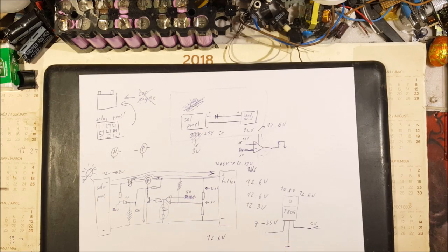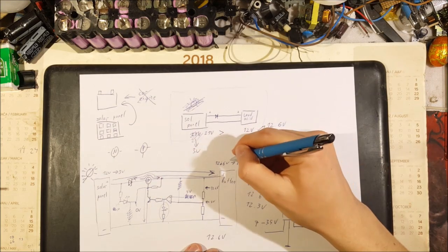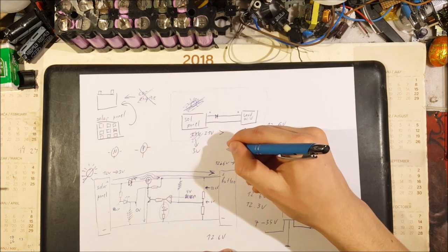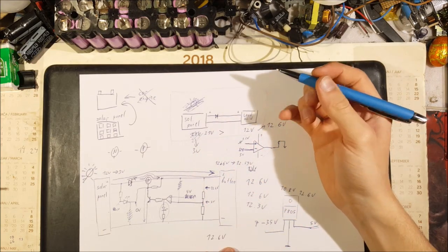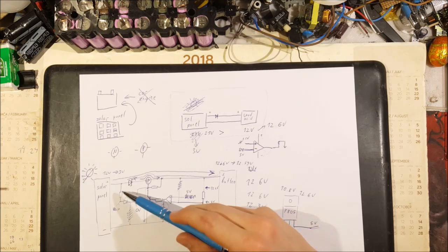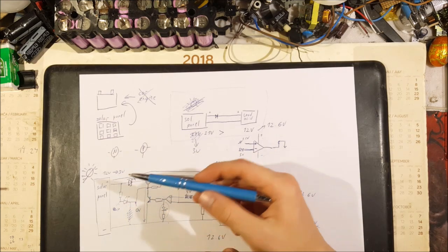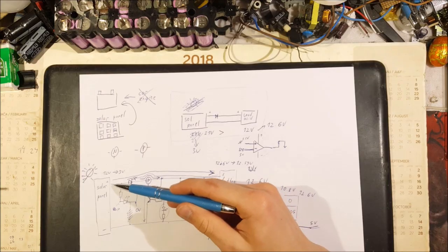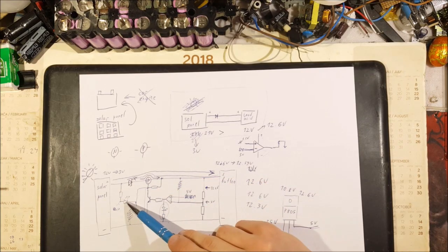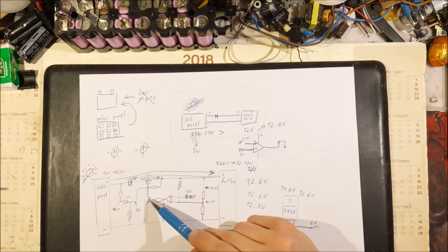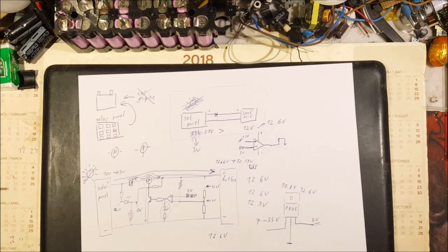and the diode won't illuminate. And when the voltage of the battery drops because it's not being charged, this transistor will turn on, and the current will flow through the positive, through the resistor, through the diode into our transistor, and the diode will illuminate.